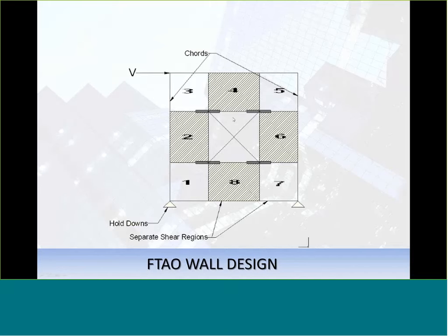This force transfer around that opening is where you're going to be putting straps in to design that, and we're going to give you the actual FEA forces that are happening across that span right there, where we're tying that opening together. So again, force transfer around openings, or FTAO as we shorten it. It's easier to say. But this also gets hold downs at each side of the wall.